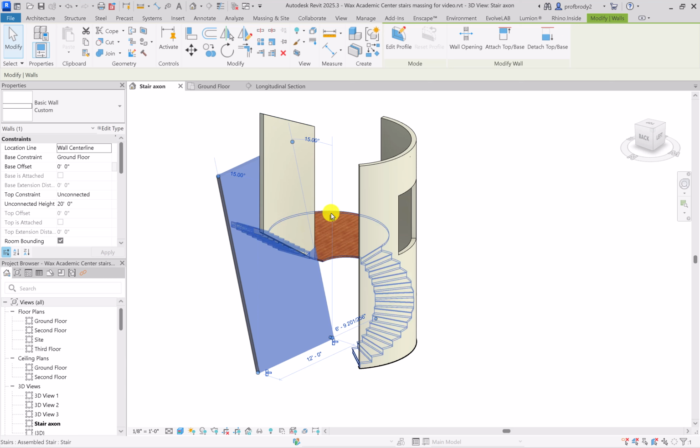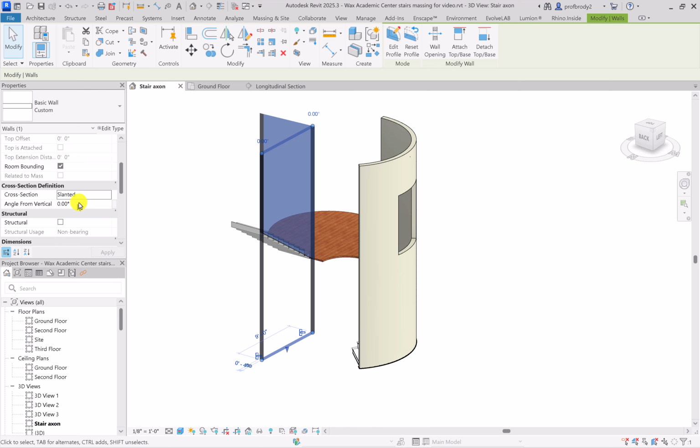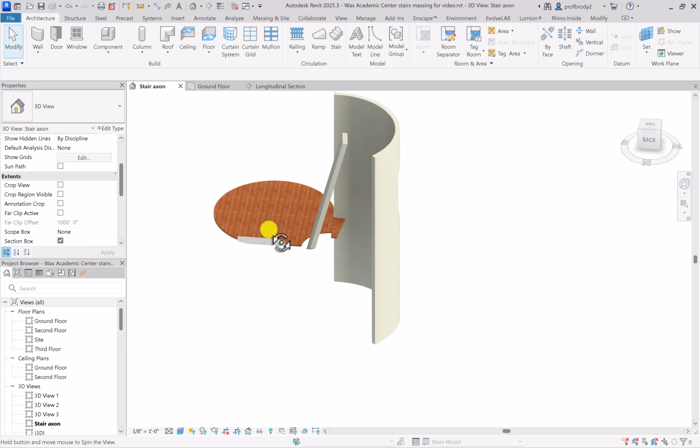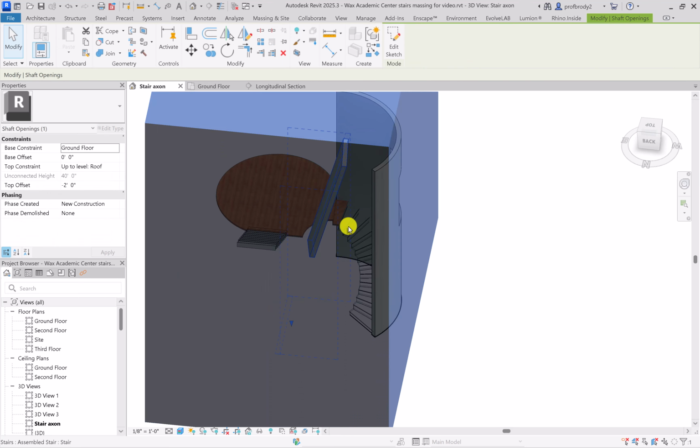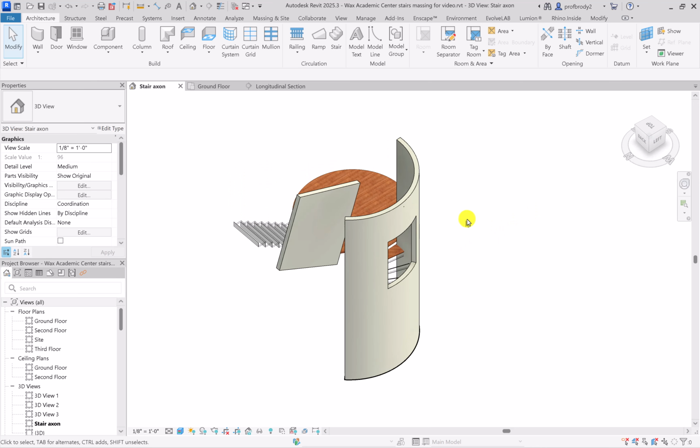It obviously does take a little bit of effort to get things in the right position, especially on certain parts of the wall. We can change it here in the properties. Getting the angle just right and getting it to match your wall is a little tricky when you've edited the profile. So this is a fairly simple, but not always the most valuable, method of creating new wall types. However, what it is really good for is if you have a railing that is all glass and you don't want any gaps, or you just want repeated gaps, you can absolutely do it this way.